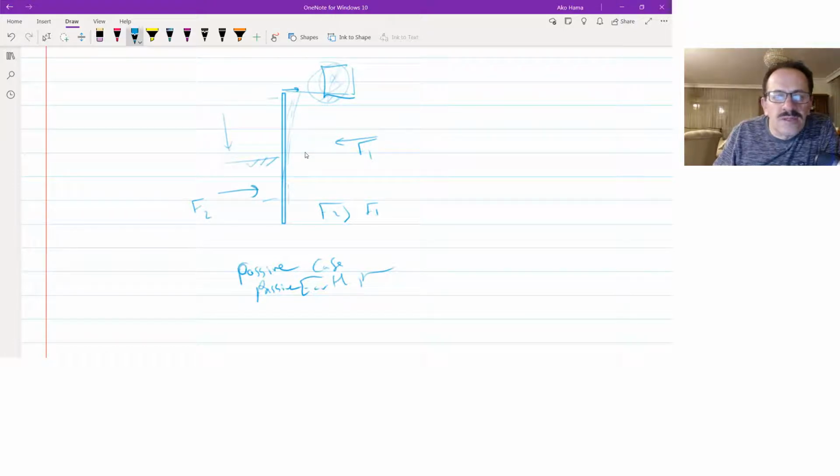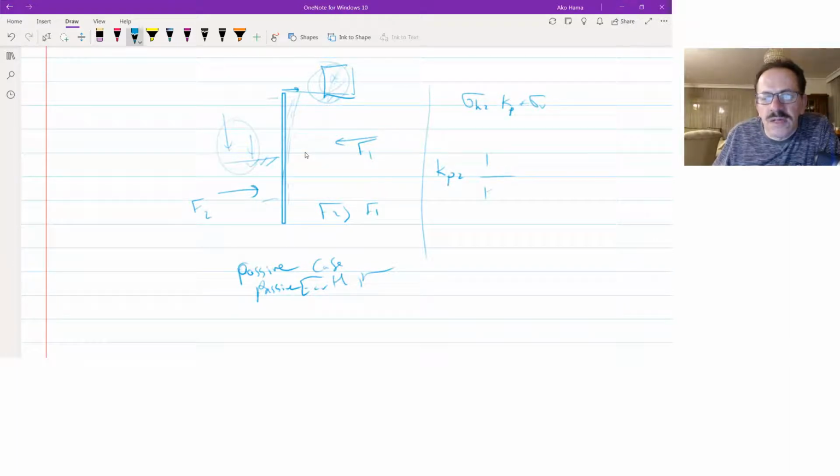So it will, for us, it will keep us, we can construct our building here, but it will affect this one. Now, what is the magnitude of the lateral earth pressure? The lateral earth pressure, again, at any point is equal to K times sigma vertical, and this is going to be Kp. What is the value of the Kp? It is 1 over K active.